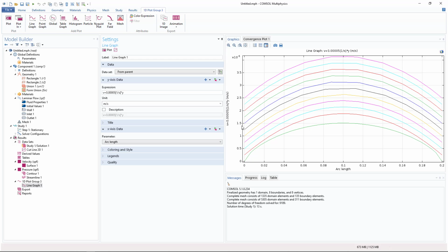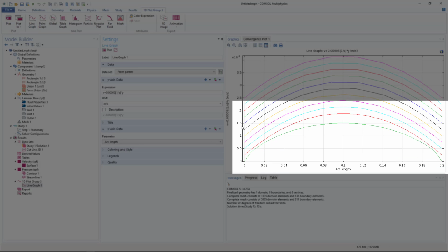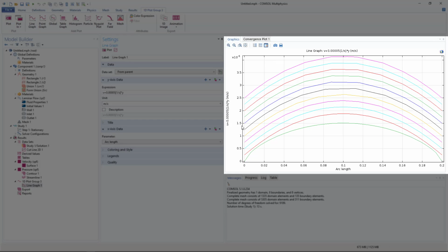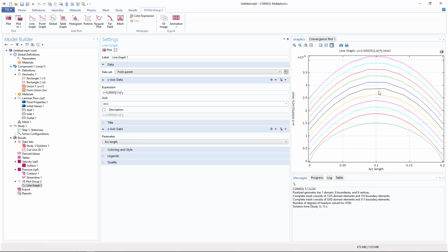Here we see that the velocity profile is definitely changing early on at the bottom. The first profile is relatively short and squat, bowed outward from a more flat profile in the middle where the parabolic behavior is not yet set in. It doesn't take long, however, for the profiles to decrease more on the outsides and squeeze the maximum velocity higher into the middle and then become perfectly parallel when they are fully developed. This is perhaps easier to see by rescaling the graphics pane to make the profiles narrower and steeper.